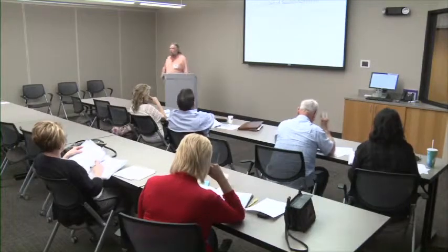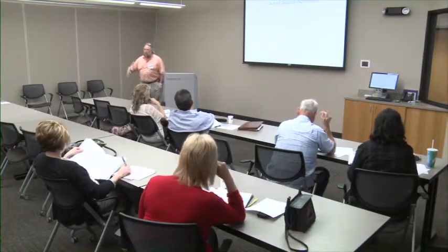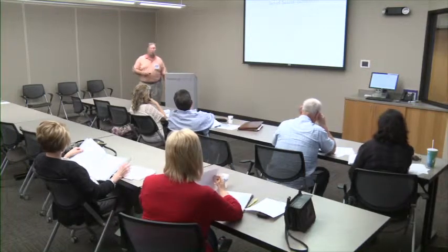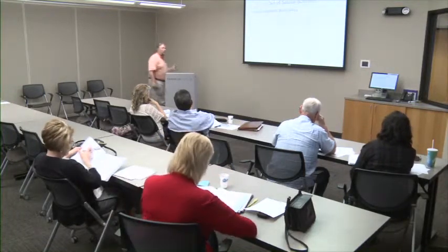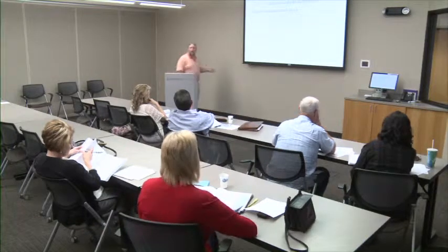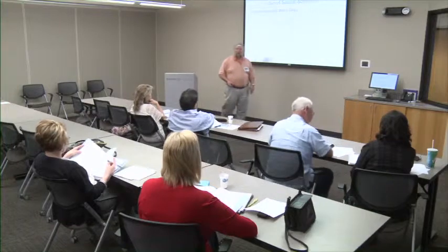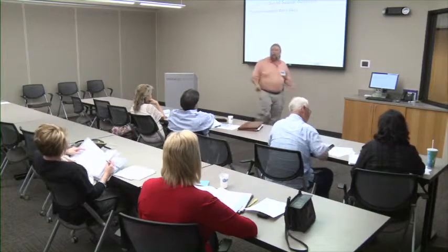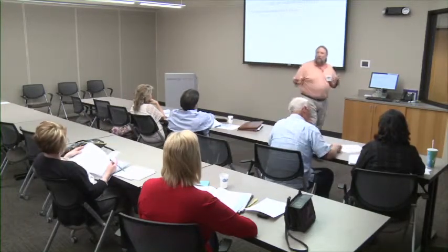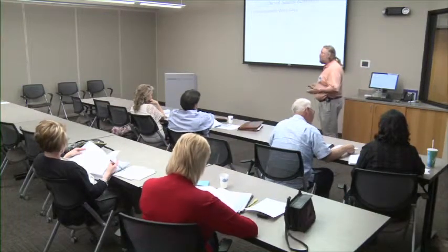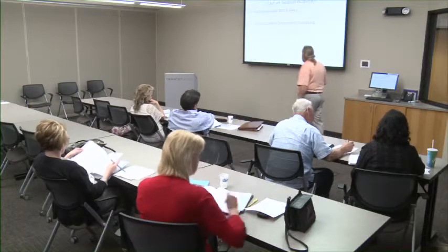Okay, one of the things to deal with in scheduling is out-of-season work. And since part of this is to talk about scheduling things that can cause you problems, out-of-season work is something you need to look at. One is you just limit your work days. Come springtime in Oklahoma, the likelihood is it rains every other day. So instead of a 5-day work week, we have a 3-day work week. Okay, we've accommodated for the fact that we're just going to be off on certain days because we think there's going to be rain. So we limited the work days.